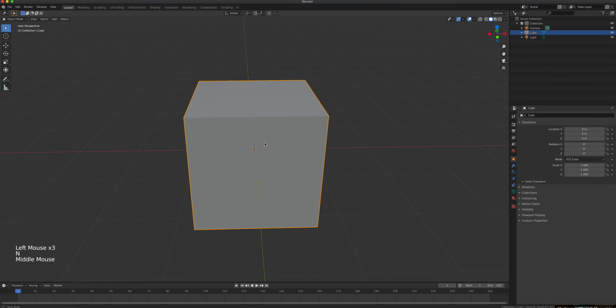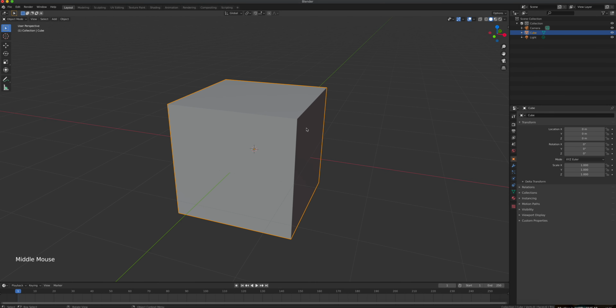All right, so when you have an object in Blender selected, you're operating in object mode. If you look at the upper left corner right here, we have a down pointing arrow, or a chevron. If you click that, there are other options here. The two important ones for now would be object mode and edit mode. These two modes right here. The keyboard shortcut to toggle between those is your tab key. So if I click tab, it switches to edit mode. If I click tab again, it switches to object mode.